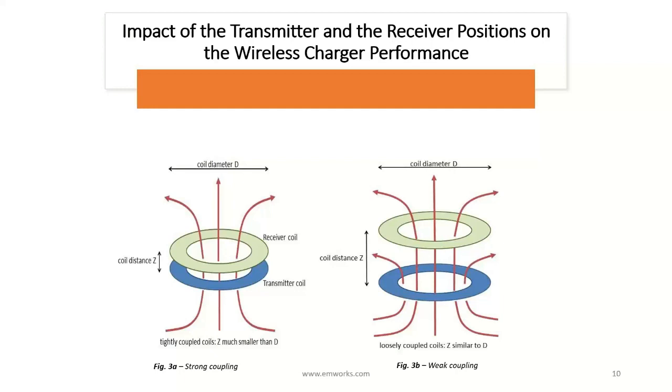So after having an idea about EMS for SOLIDWORKS, we can now move on to study our wireless charger system for a pacemaker. We are going to start by seeing the impact of the relative position of the charger coils. Both the transmitter and the receiver positions play an important role in the performance of any wireless power system, not only in this case of implantable devices. It affects mainly the coupling coefficient, which also has a great impact on the receiver output voltage.